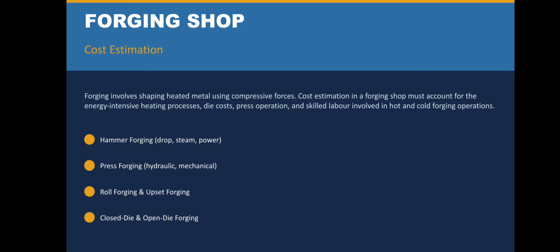Also, the estimation of material losses in forging includes shear loss, tongue hold loss, scale loss, flash loss, and sprue loss. These are the losses included in the estimation of material losses in the forging process.